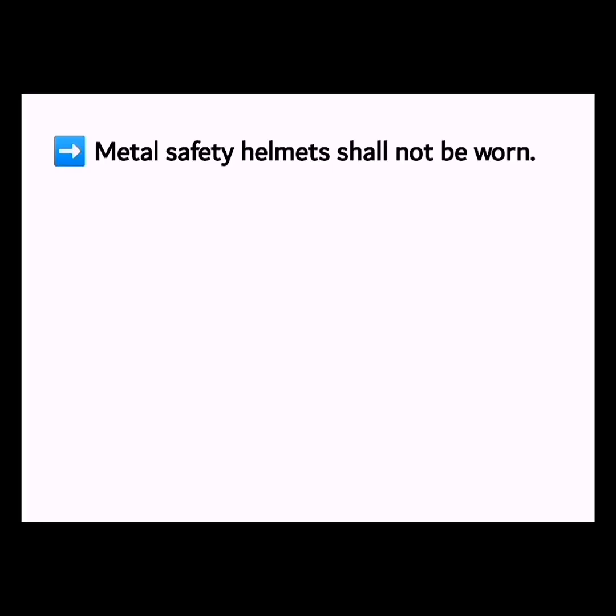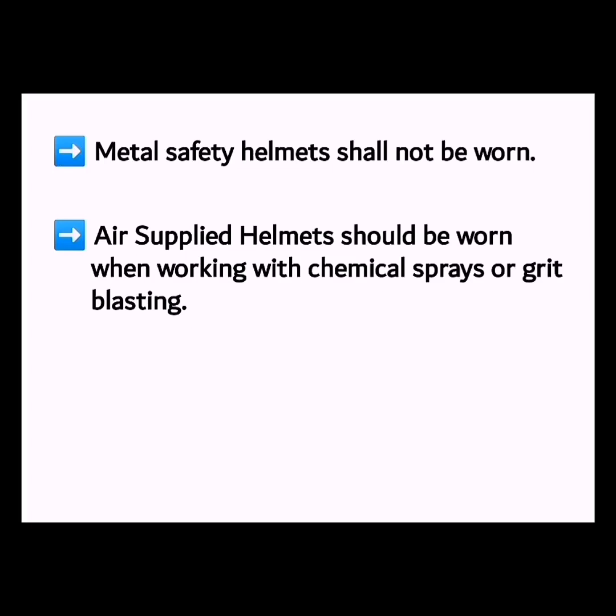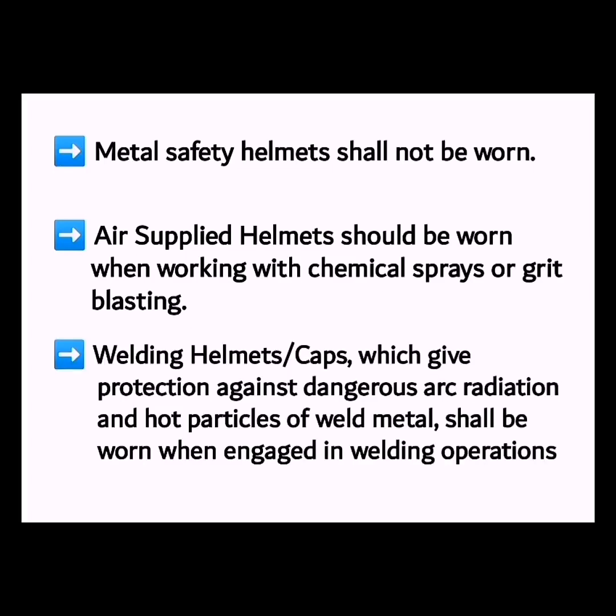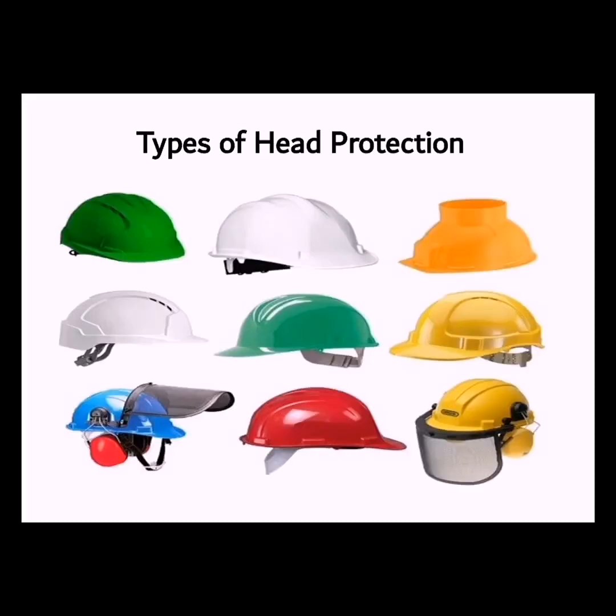Types of head protection. Metal safety helmets shall not be worn. Air-supplied helmets should be worn when working with chemical sprays or grit blasting. Welding helmet caps, which give protection against dangerous arc radiation and hot particles of weld metal, shall be worn when engaged in welding operations.